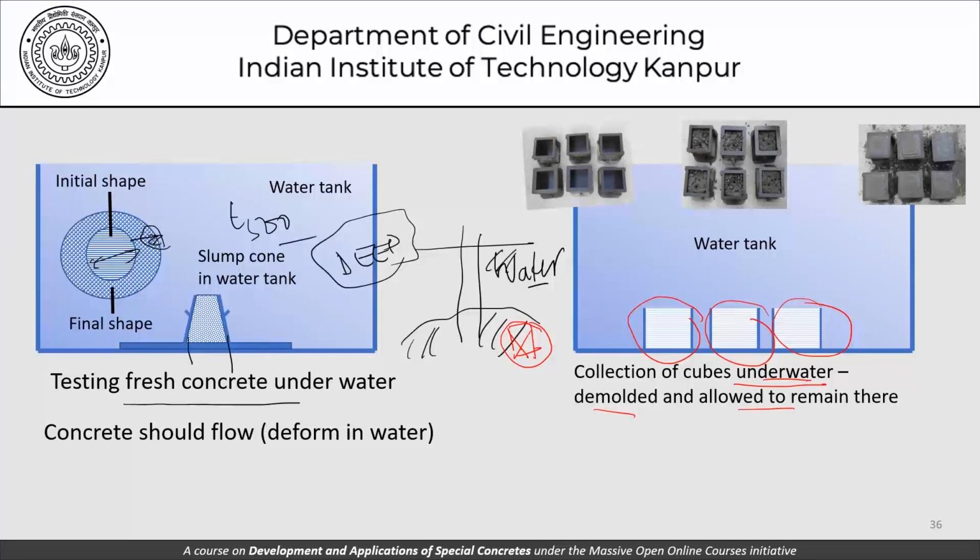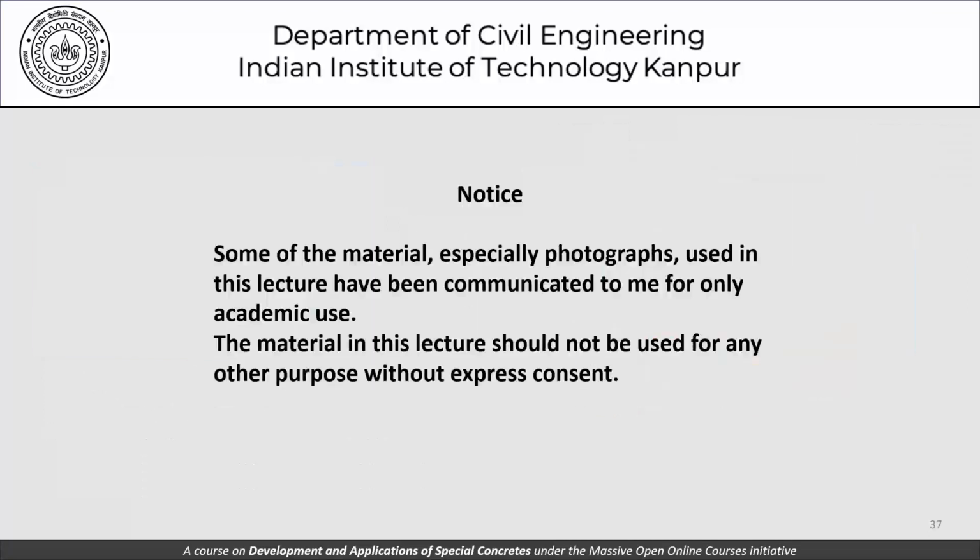We cannot possibly test the concrete underwater. We'll take it out momentarily, for a very small period of time, and test it in air, but at least the sampling and the curing happen in water, the sampling particularly. Now with this, we almost come to an end of our discussion today.